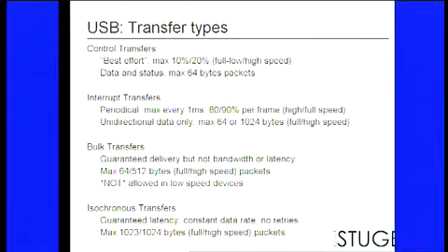It's command response or request reply. I have some numbers here on how much bus bandwidth they are allowed to occupy. I have a lot of slides, so I'm going to skip over that, but you have the numbers here. Control transfers are delivered on a best effort basis, so it might take a while before they actually go out, but they will never be lost. There's a limit on the data you can send as well.